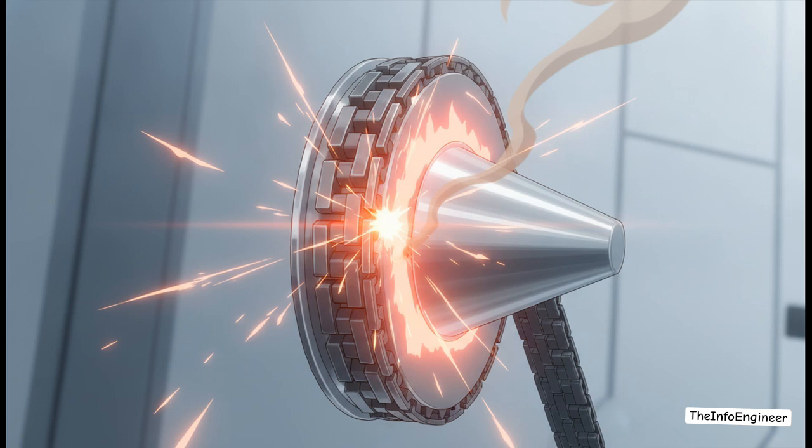See, unlike traditional transmissions that rely on the unbreakable physical barrier of interlocking steel gear teeth, CVTs rely entirely on friction, and friction is absolutely everything here. If the belt slips against those smooth conical pulleys under heavy acceleration, you immediately lose power, you generate catastrophic heat, and the transmission essentially destroys itself.